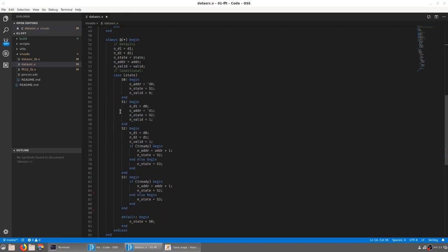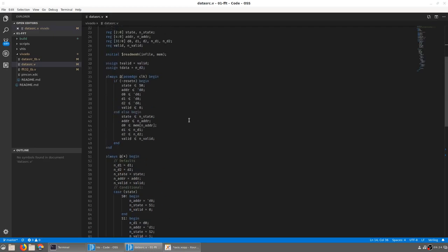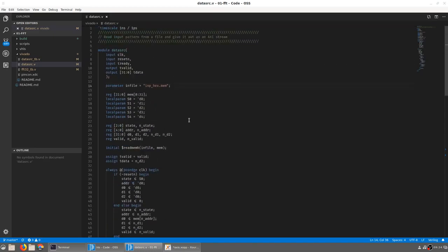It has multiple states, mainly to account for the fact that the block RAM in which the data is stored has a certain read latency. But apart from that, all that it does is it basically starts putting out data, and from that point onwards, the valid signal is permanently high. It only then responds to the ready signal coming from the slave. By doing this, the simple module is able to send out data that can then be consumed by our FFT module, or as we will see in the final design, by the expected data output in the test bench as well.